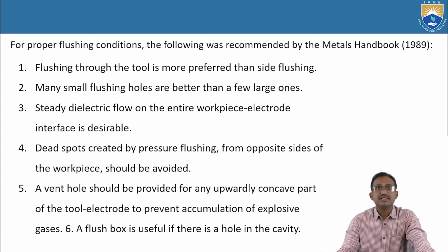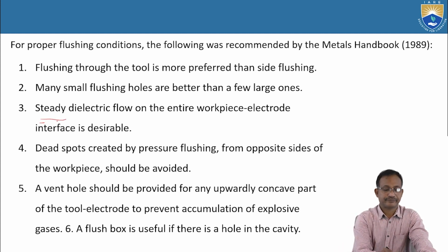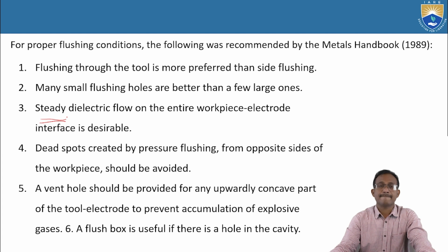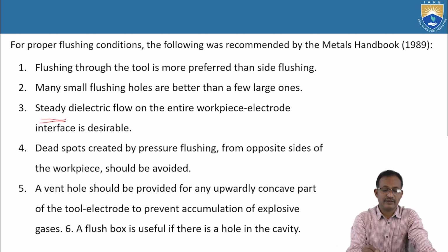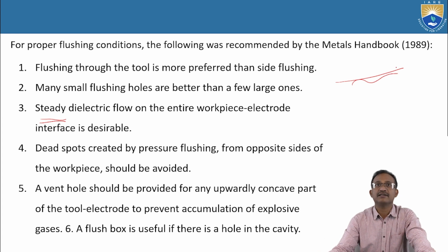Third one, steady dielectric flow on the entire workpiece electrode interface is desirable. So it must be steady. So here always a steady flow of the dielectric on the entire workpiece electrode interface is desirable.